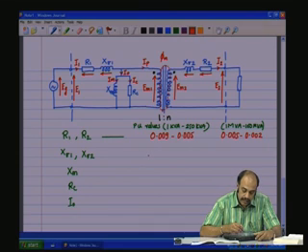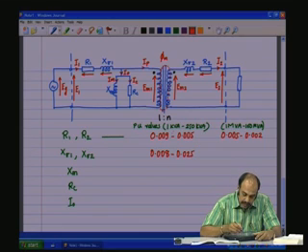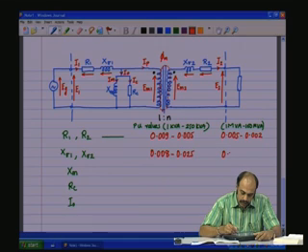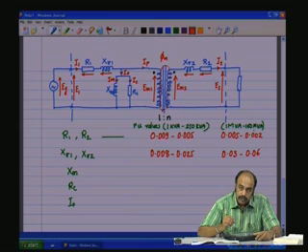And the leakage reactances have the per unit values of 0.008 to 0.025. The per unit value at around 1 kVA is 0.008 and at around 250 kVA is 0.025, and 0.03 at around 1 MVA and 0.06 at around 100 MVA.